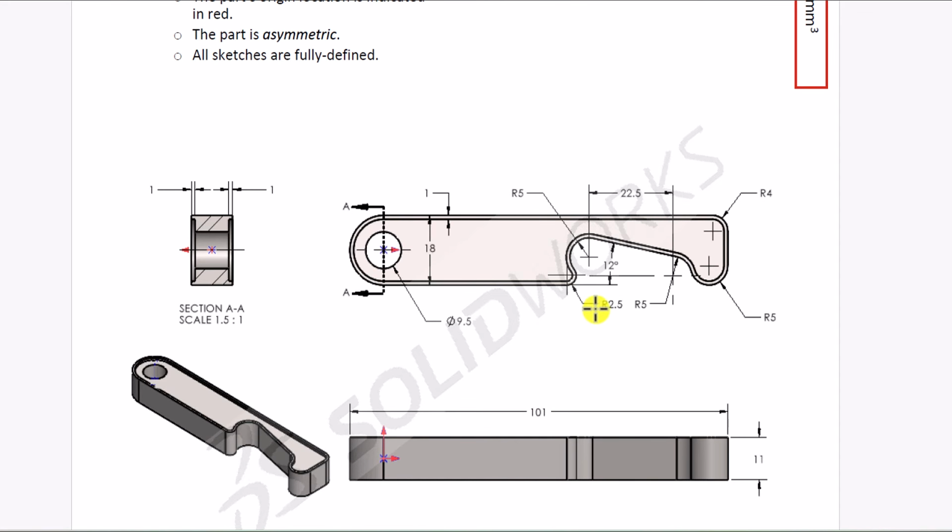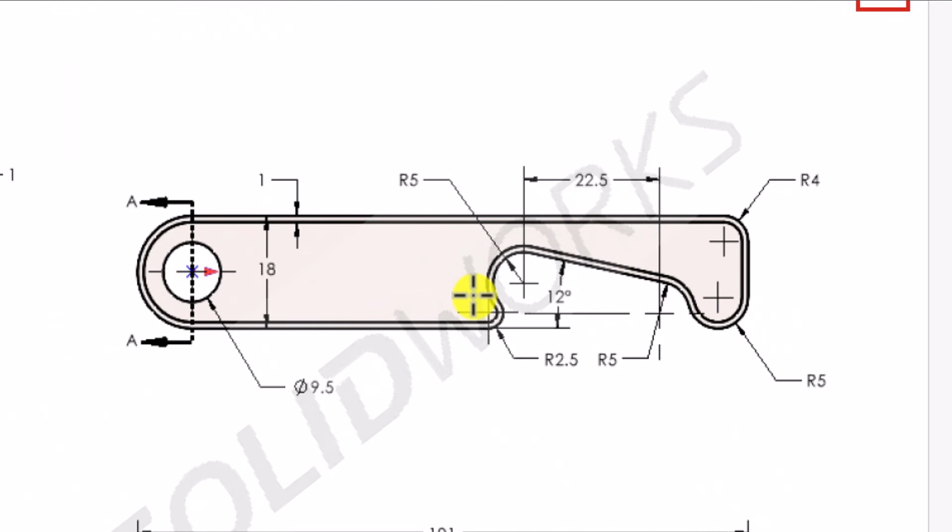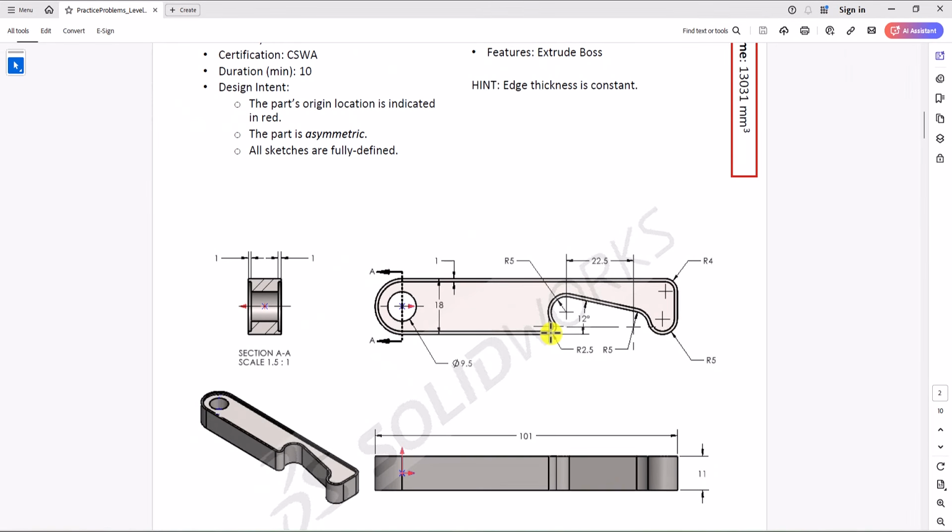If you're looking at the arcs that we have here, again, these plus signs that you see are center points of the arcs. Now, if you focus on arc number 2 and arc number 4 here, you can see the center point of arc number 2 is in line with the center point of arc number 1. So we have to make some sort of assumption. When I'm looking at this geometry, I see this as the most reasonable assumption we can make. So let's add this constraint to our geometry and see if this can help us have a fully defined geometry.